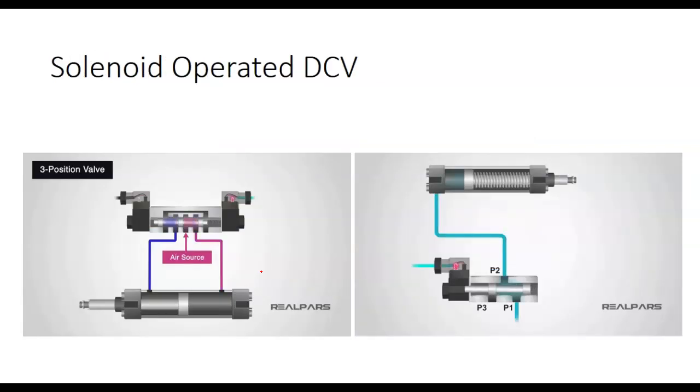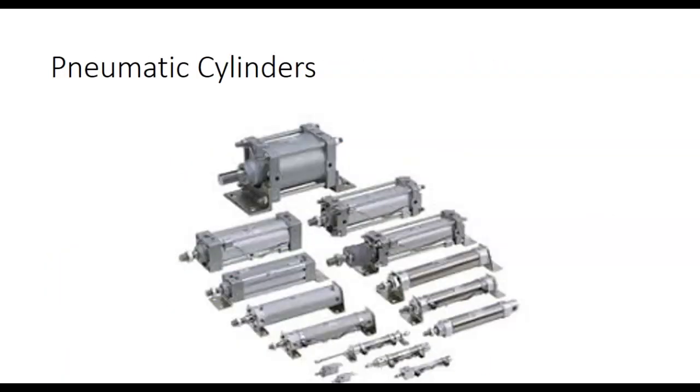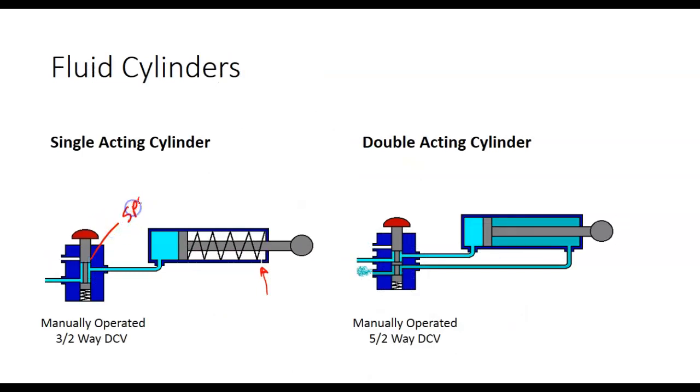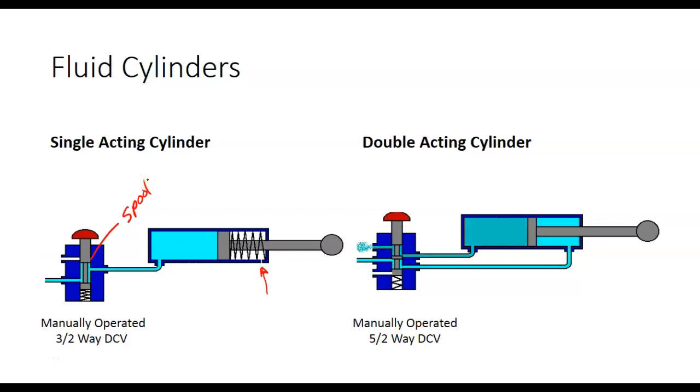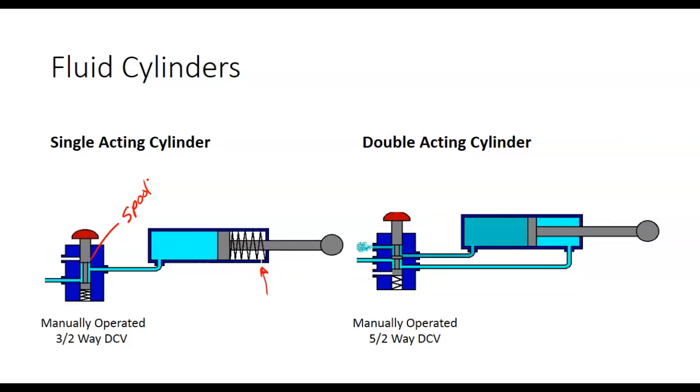So we have to have something. This unit that's moving, originally it looked like one, but the unit that's moving inside the cylinder, we refer to as a spool. On the Amatrol line over there, we have the spools that we fit in there. It's got gaps in it, and we position it, and it literally routes which way the air or the fluid flows. That would be more correct.